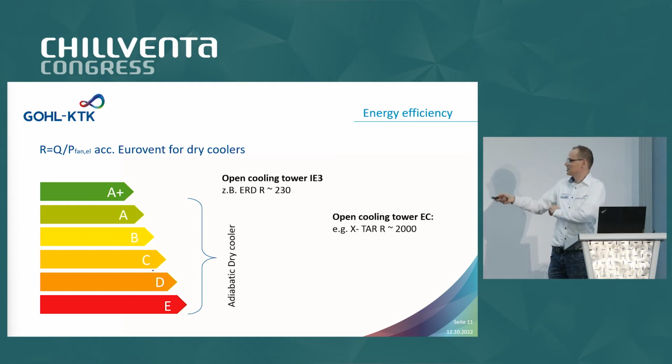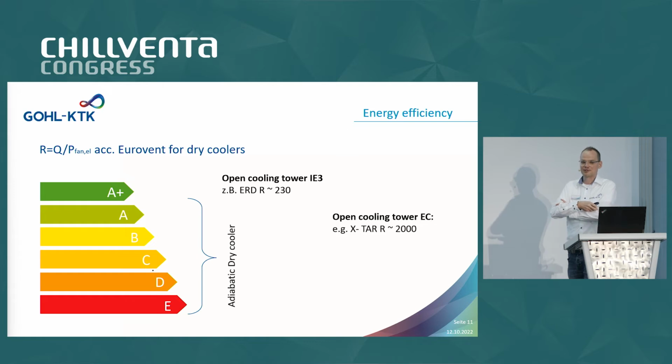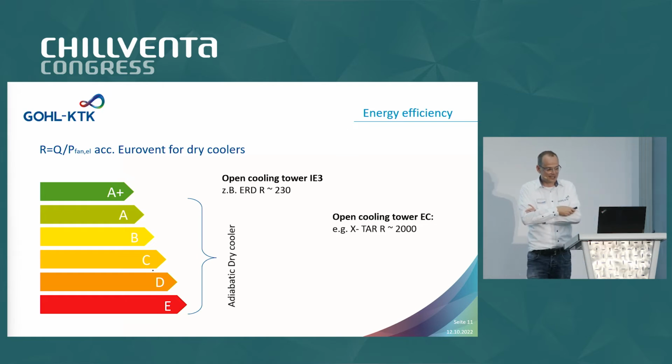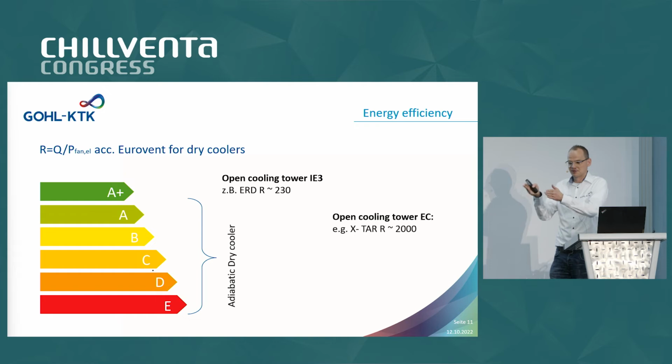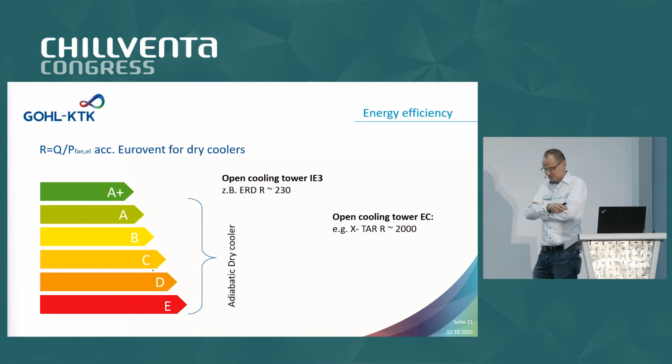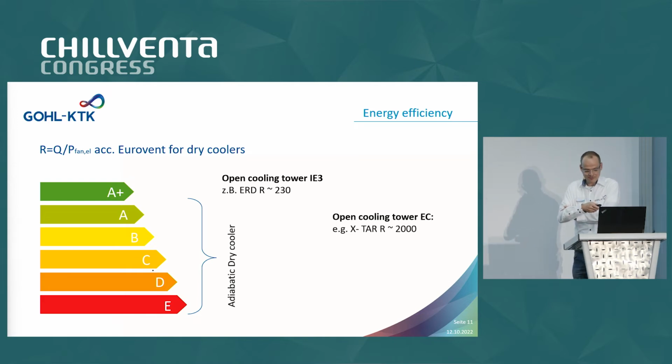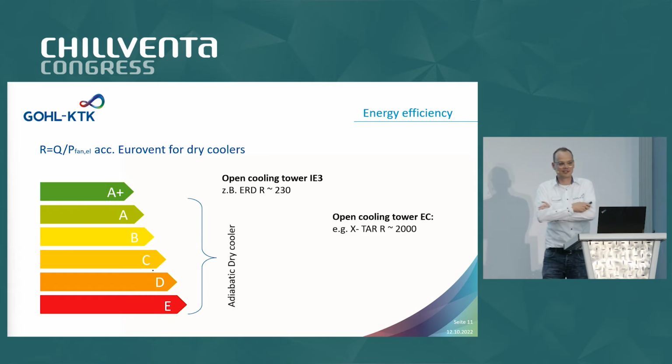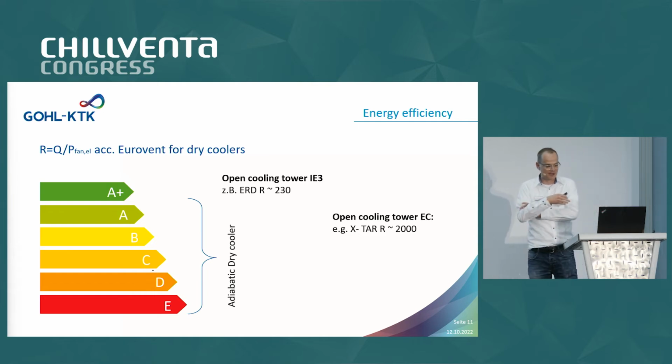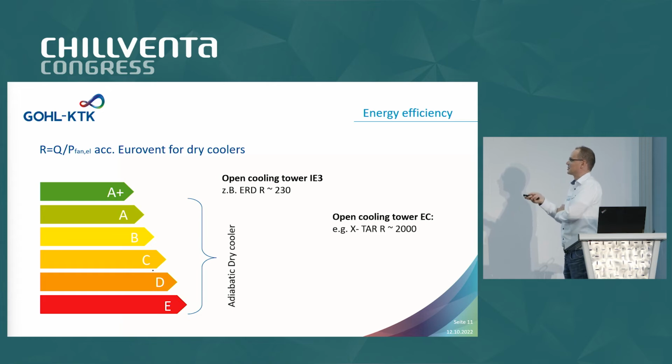With the adiabatic coolers, we normally reach similar values of energy efficiency like dry coolers, because as I told you, it's the same principle. We have a traditional heat exchanger coil and we only have the evaporative pad in front of the heat exchanger, so it's quite a similar process to a dry cooler in terms of energy efficiency. Of course, when we go further afterwards, the effects on the refrigeration plant, the energy efficiency will be better of an adiabatic cooled system than a dry cooled system. But that's not the question of the comparison in that sheet.